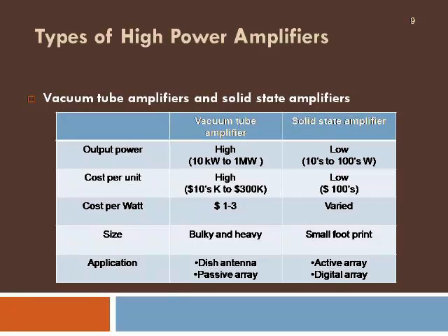Normally we use Klystron or TWT amplifiers, and we can get power output of the order of tens of kilowatts or even megawatts. If you are going for several antennas working together like a phased array, we can consider solid state amplifiers as the choice, wherein the power output is low, in the range of tens or even hundreds of watts.